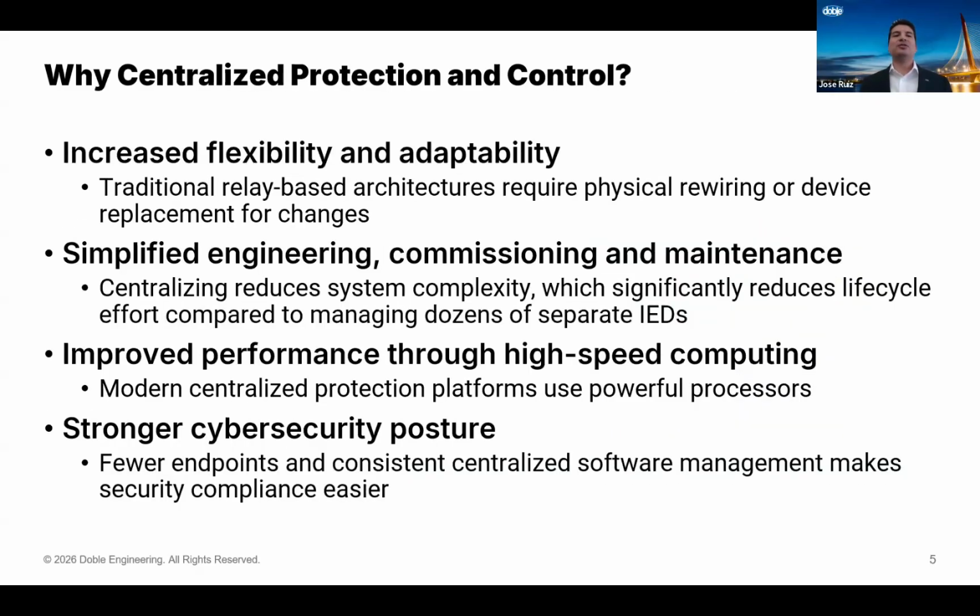Now, why centralized protection and control? Why might you want to consider centralized protection in your next substation project? Number one, it increases flexibility and adaptability. What is the meaning of that? Traditional relay-based architectures require physical rewiring or device replacement for changes. Maybe some of you might say, well, I'm able to do that with a microprocessor-based relay using IEC 61850. And that's true, because we no longer have hardware connections if you are using IEC 61850. So that's something similar to what we are able to achieve with the second generation of microprocessor-based relays.